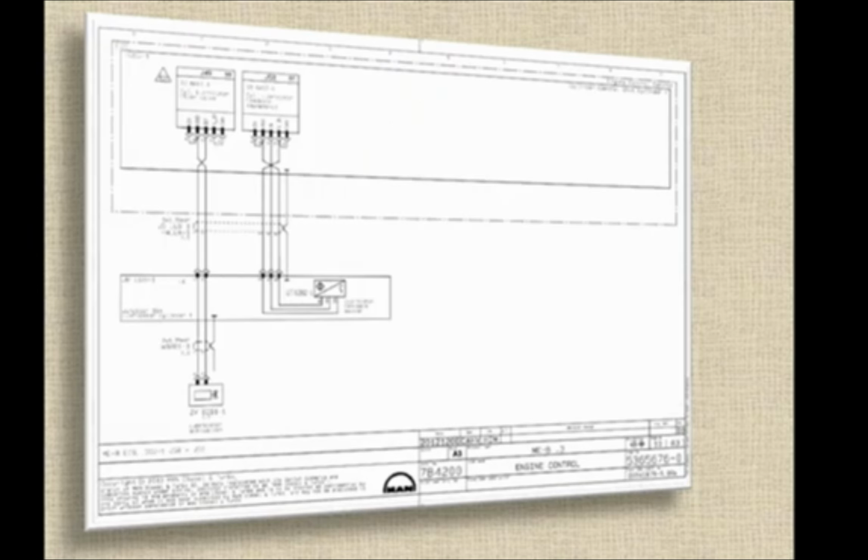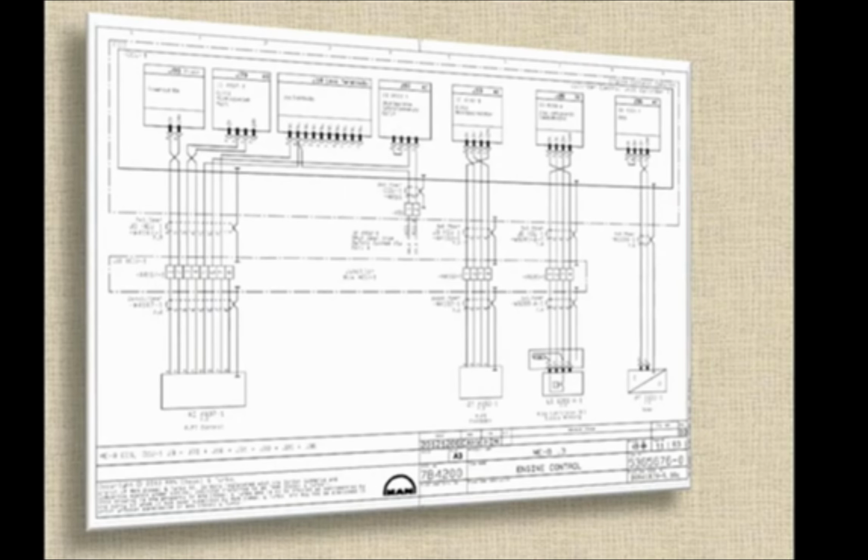And for reference I gave some CCU1 plug details from the channel side, and you can see that each wire number and everything is noted here, and with that we can trace the wire. If any wire has trouble or anything, you can easily find out, and all channels are available in the circuit diagram. It's very easy to trace out.